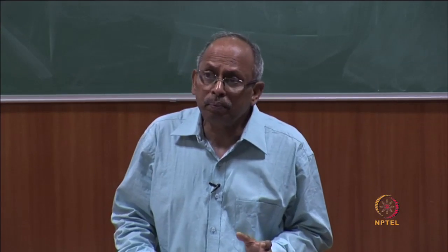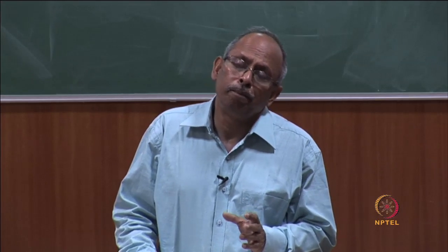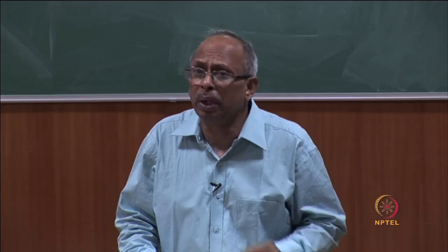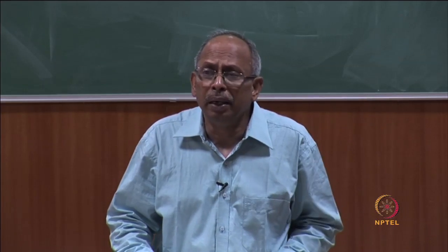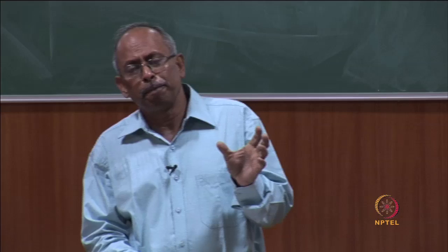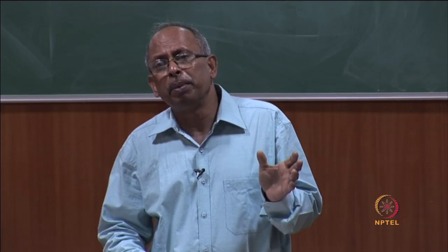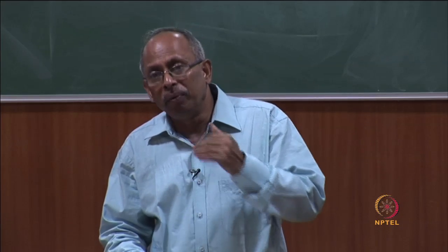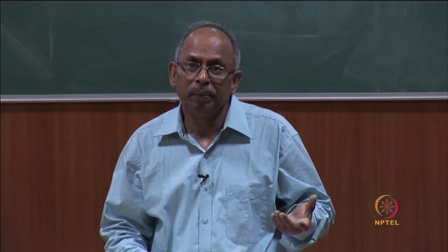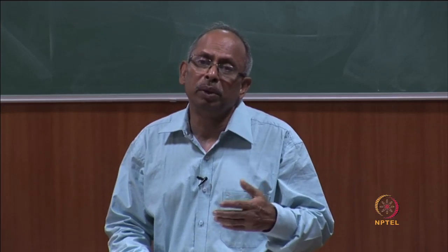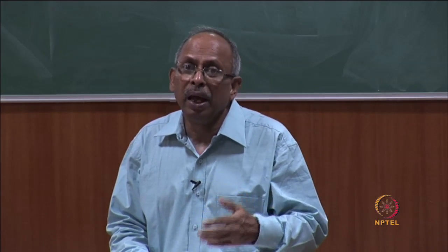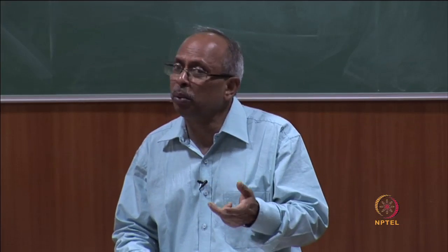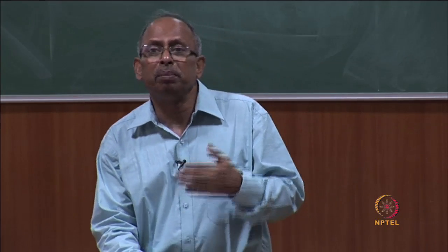Consider, let us say, any part of the composite monsoon climate of central and northern India. You have a monsoon season of 2 months. During this time period wetting will continue, but after that drying starts, and before the monsoon season it was fully dry. During the monsoon season wetting would start and the concrete will become moist, and if the situation is conducive for the cover concrete, carbonation will progress, and when winter comes, it becomes more dry.